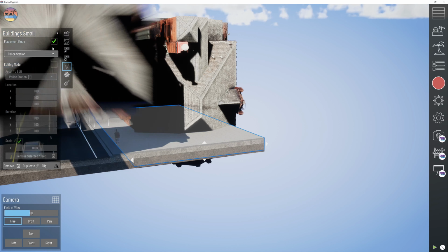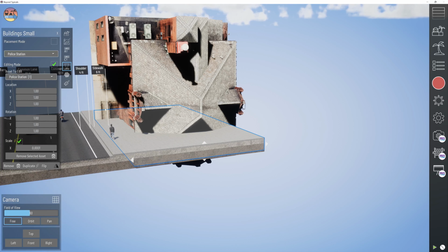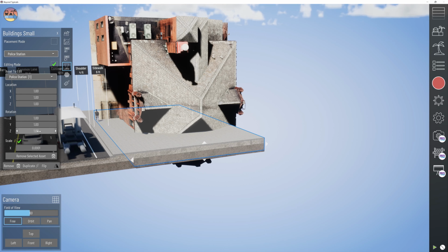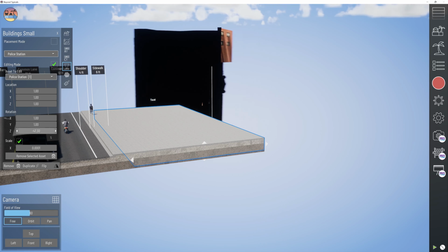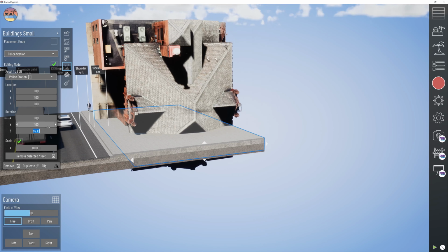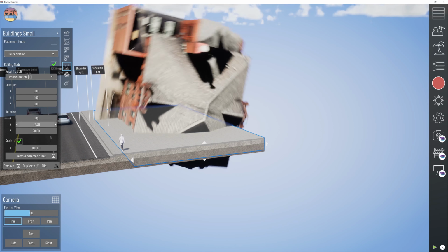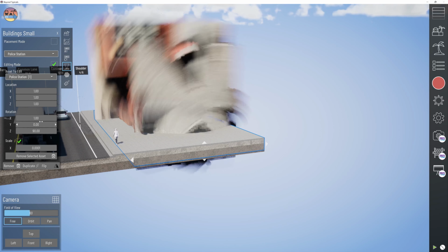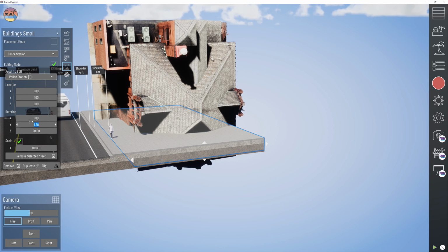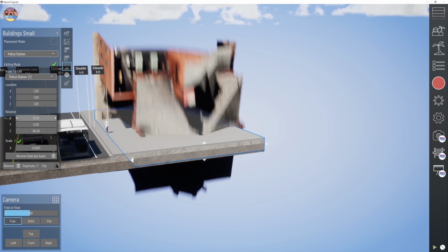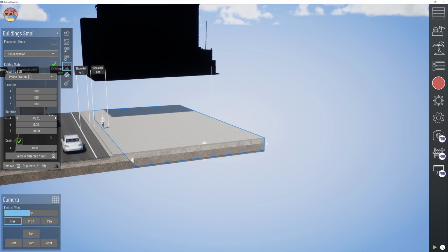We notice that it's rotated incorrectly, so we could go back and re-import, or we can rotate it here. And just note, once you import one time with your own workflow, if you can keep notes, then it should use the same settings for future importing. All right, so let's leave that at 90, and let's leave that at 0, and then see what happens with X. All right, so we want this to be -90.